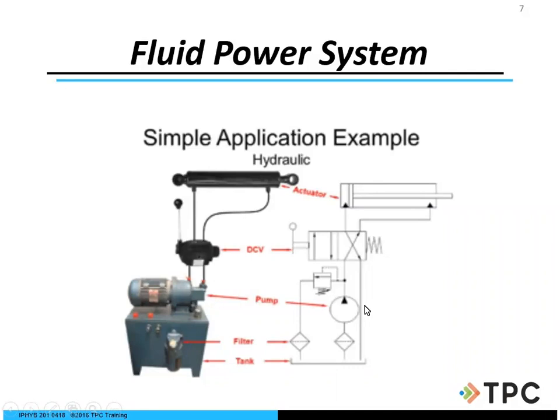All right. So usually, as we've shown here, this is our pump, but this is our motor over here. It is critically important to know how our motor is really connected to our pump. We have a direct coupling, a close coupling with the motor to the pump, or we have other couplings that we can choose from. It all depends on the application. I don't get too much into it, but we have our motor and our pump. Alignment is critical. As a matter of fact, misalignment is the number one failure in the United States in manufacturing.